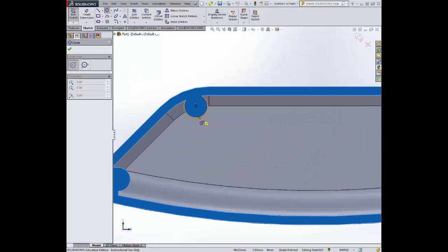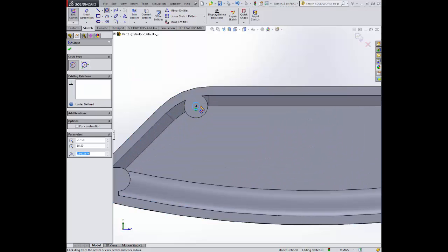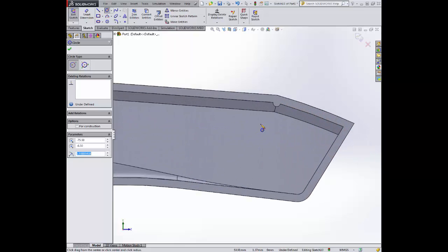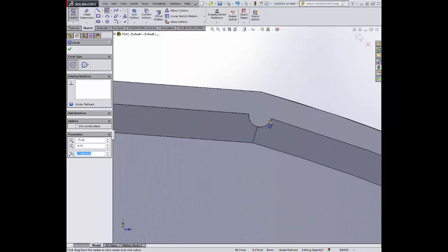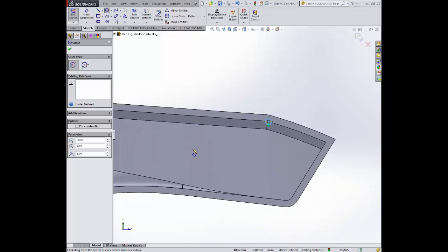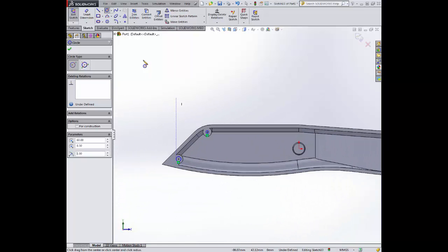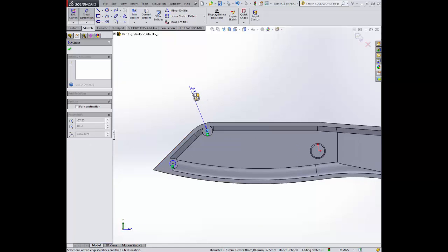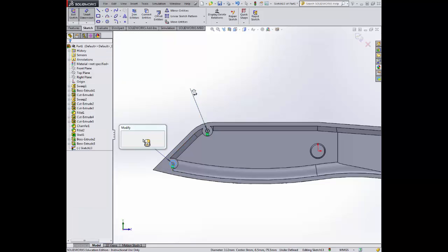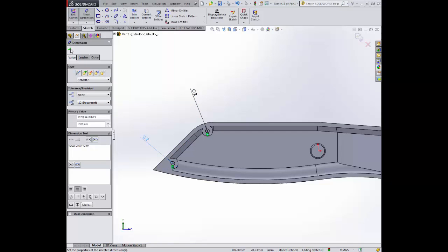Now if I roll around the edge of this, it will give me the centre point, and my cursor will automatically snap to it. So I'm going to do that for each of those. As I already said, this first one wasn't necessarily the only way of doing this particular circle, but this will do here. And 1, so it's exactly the same as the original. Zoom into these and make sure they're the right size too. So 2 is a diameter, 1 is a radius, depending on which dimension you're using to do this.